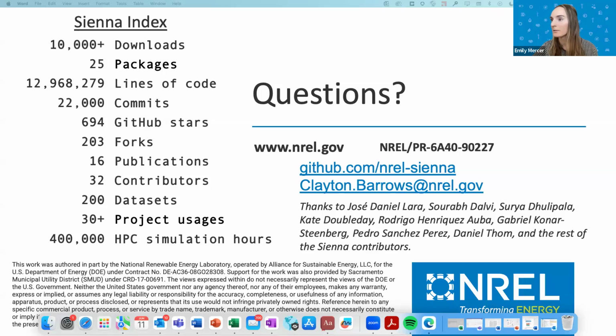Awesome. All right, next question. What scale can Sienna handle for instantaneous or snapshot DC power flow scenarios? Did I hear correctly earlier that you ran such a simulation for the entire Eastern interconnection? Yeah, not just the entire Eastern interconnection. We've done a snapshot for a representation that includes all of North America. So it's a 120,000 node simulation or something on that scale for a single snapshot DC power flow. We can do unit commitment and dispatch on roughly a 75,000 node representation of the Eastern interconnection. And I don't think we've tried to do a full continental scale one yet for that. So, large.